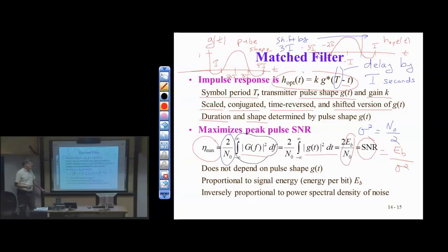Now this is important because in a communication system, we have certain SNR operating points. Based on the channel conditions, we are going to operate over some range of SNR. So if we want to test the system that we've designed, the transmitter and receiver, we have to pick a range of SNR values over which to test our design, simulating in MATLAB to start with.